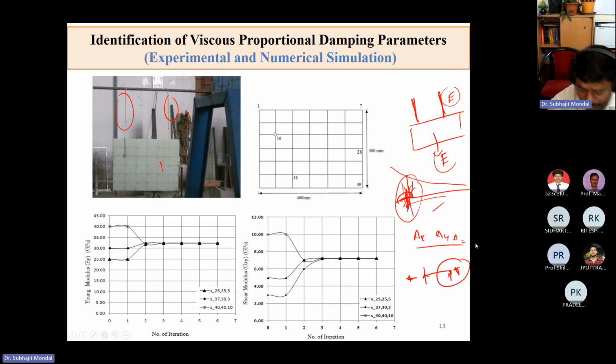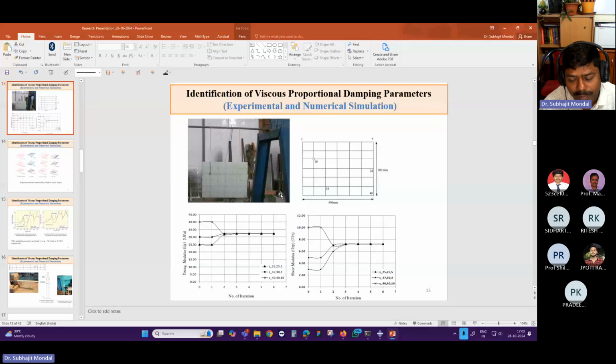So if you go for any analysis in the dynamic domain or for vibration analysis, you should go for either free or fixed conditions if possible. If you are forced to use simply supported conditions, then you have to take proper precautions and make sure you are achieving the ideal simply supported conditions. You should then compare the response obtained in the dynamic domain from the experimental data as well as the numerical data.